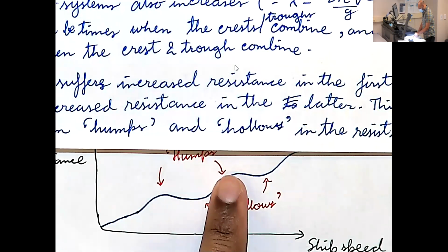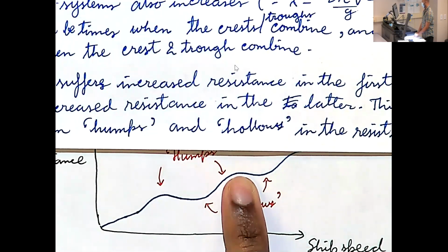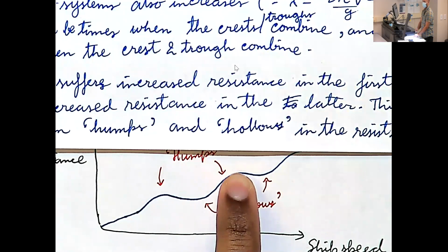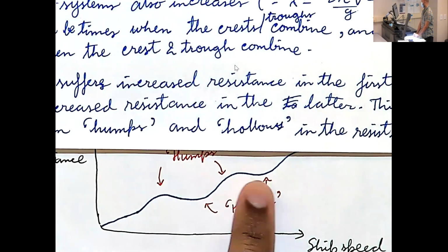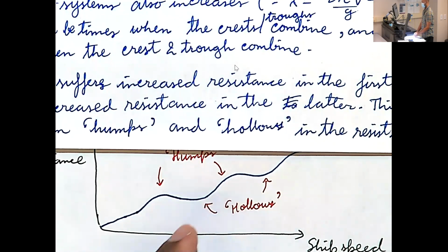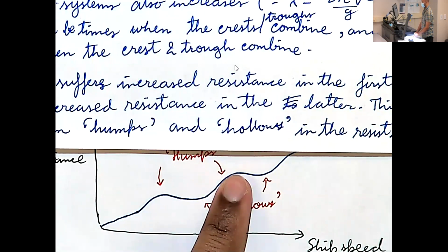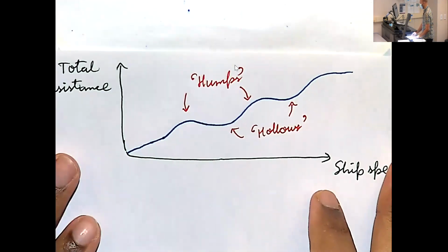20 knots here, 22 knots there. What would you do if you were in this situation? Yeah, you can slow back down, or you can go even faster. If you go faster, you're not consuming any more fuel. Your drag doesn't increase, but you cover more distance in the same time. So knowing this sort of a curve helps you optimize your speed and drag. And all of this is due to wave drag.